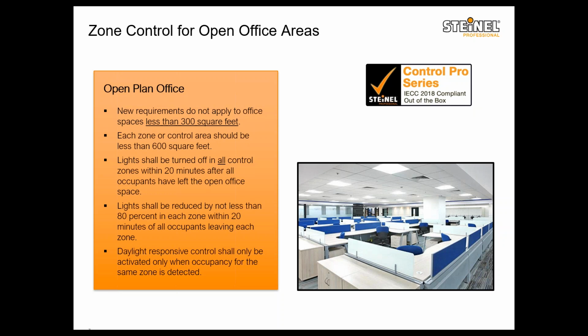So this is really the main part of this new requirement. And then there is a little bit of clarification about daylight responsive controls in these open office areas. Daylight responsive control shall only be activated when occupancy for the same zone is detected. So not only are we dividing up the office into separate zones, the daylighting zones are going to be split and confined within that zone as well. We'll see that better in the next slide on a layout that I have prepared for us.